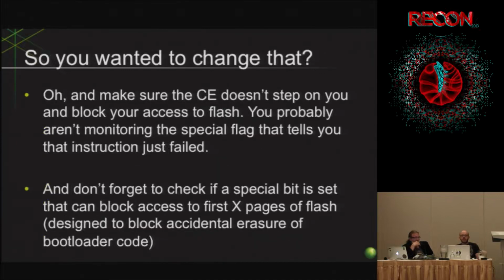All right, so the other stuff that matters on this particular platform: if you don't turn off the CE, then you get all kinds of garbled stuff, and you won't have any idea why it's not really working, because you're not seeing in your debugger all the interrupts and things that are happening, because you didn't know that you needed to pay attention to them. So the easiest thing is just to turn that stuff off.